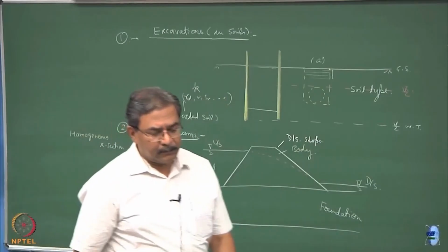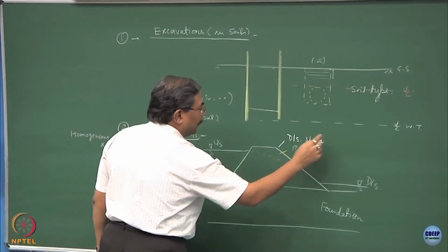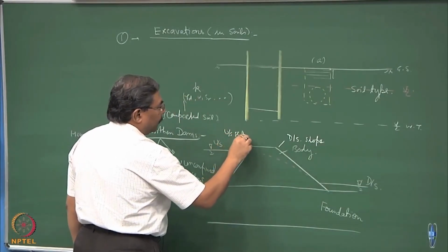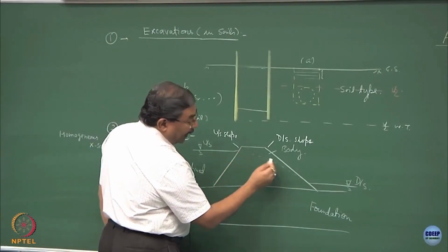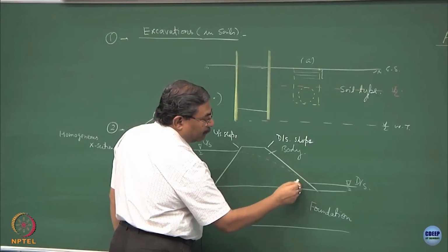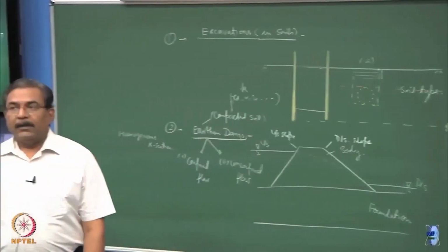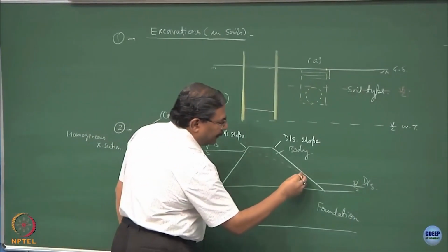And this is known as the downstream slope and this one is known as upstream slope. So, as you see, the moment this top line, phreatic line, comes and hits over here, there could be some erosion which might start from this point. Clear? So, in order to stop that, what is done is normally we design filters.